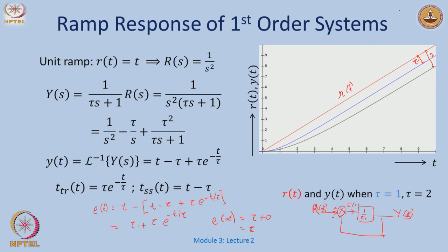How do I encounter a steady state error? Let us say I again take this example of a pendulum, and I started with some non-zero initial condition, and I expect it to go to theta equal to 0 if this is theta. But there could be something in the system which stops it from going there, maybe it just stops at theta equal to say 0.1 degrees. So, that is the idea of this steady state error. It does not really reach the desired value, but some number very close to that. There is an error, but there is a way to determine that error, how small it is, how large it is. I can directly quantify it by just looking at the dynamics of the system.